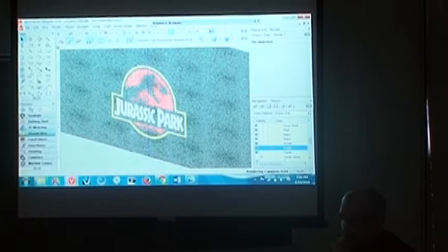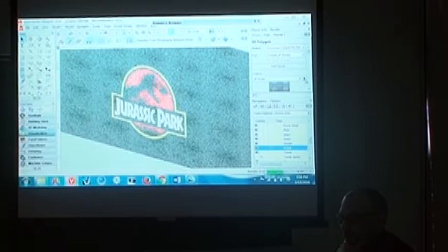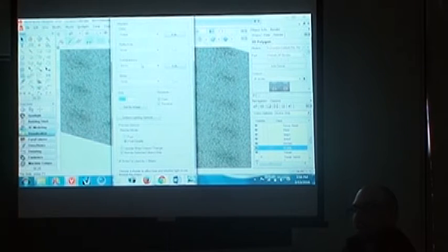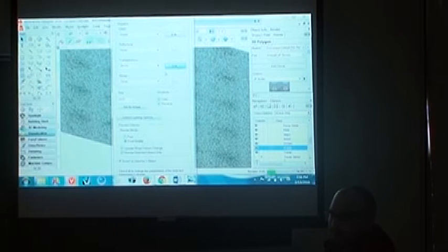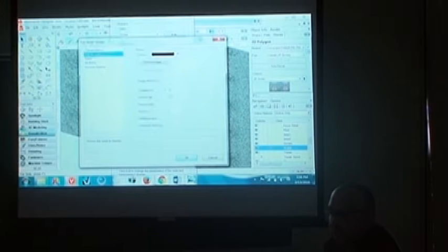There's nothing behind it right now for you to look at, but if I click on this and I edit the texture, so what I did for the transparency to create a scrim was I used this bricks option, which is basically a way of creating that black and white grid, but instead of using an image, I actually input these settings for bricks. I wrote the settings down on here so you can play around with it if you want to try it.